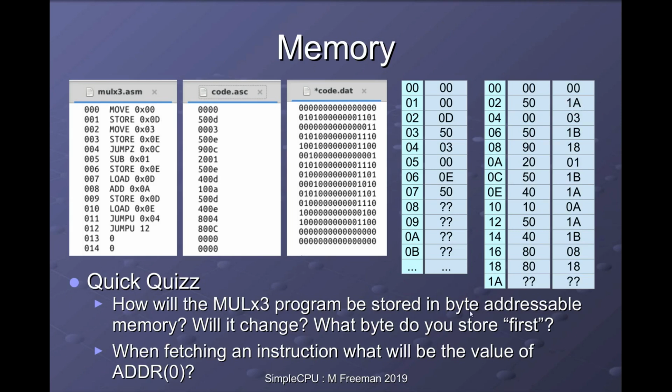And the key advantage of this is obviously we save memory. So in the original program, I needed two memory locations to store my two 8-bit values. And that was actually taking up two 16-bit memory locations, or 32 bits worth of storage. And I was only using half of that to store two 8-bit values, or 16 bits. In the new byte addressable memory, I use two 8-bit storage locations because now I can address every byte in memory. So I store one variable to address 1A and the other variable to 1B.